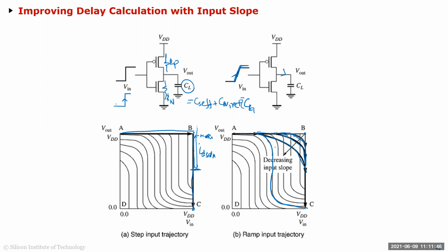That's why when people characterize it, they do spice simulation with every possible rise time, and then they take that data and put it in the .lib file. That way, when the digital synthesis is going on, it is only looking at a small file of a few bytes, not megabytes of KCL, KVL calculations of all nodes, because it doesn't need to do that now, because we have created a nice model. And that's the model we are developing here right now.